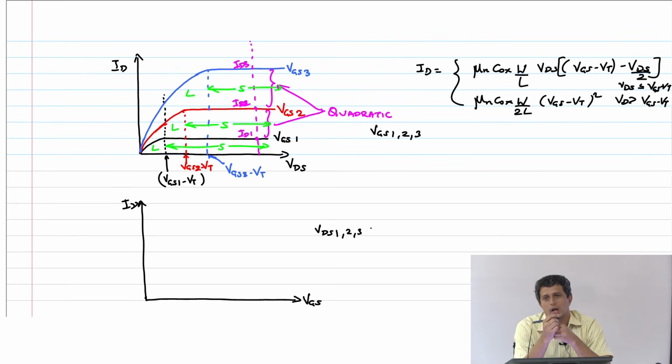So what will happen to the current if VGS just goes slightly above 0? Some small value, let's say 1 microvolt. VGS goes to 1 microvolt. Has to be 0, right? Assuming that the threshold voltage is about hundreds of millivolts, obviously the current is going to be 0. Therefore, this will be 0, right? Now at some point this will take off. What is that point? The threshold voltage,